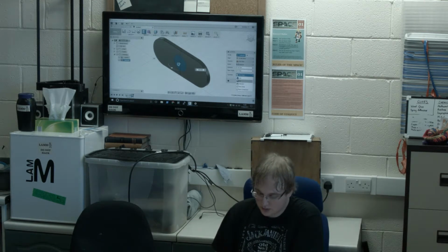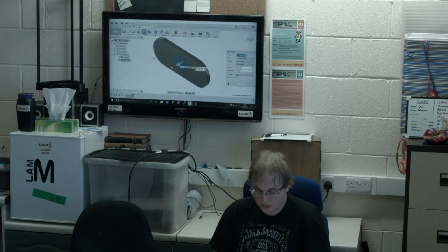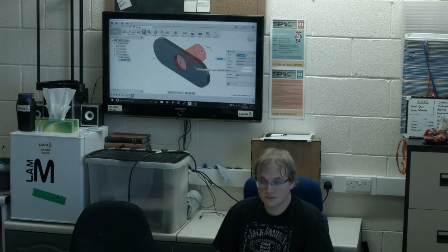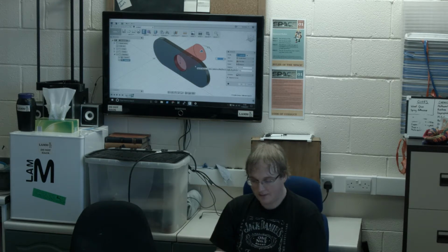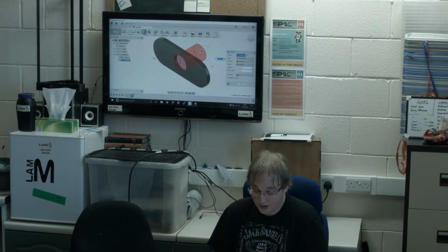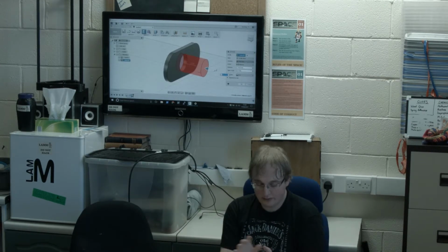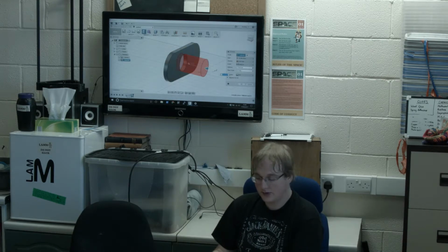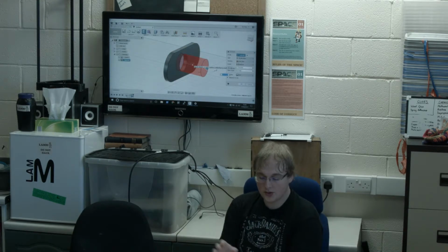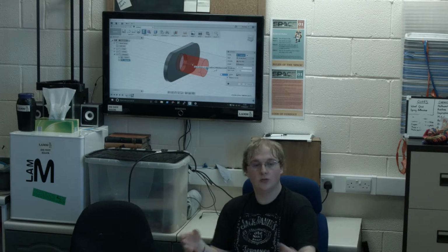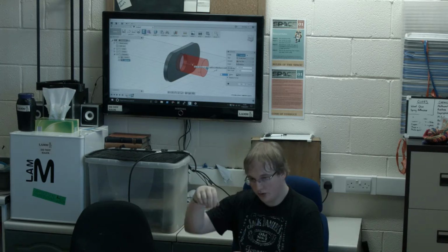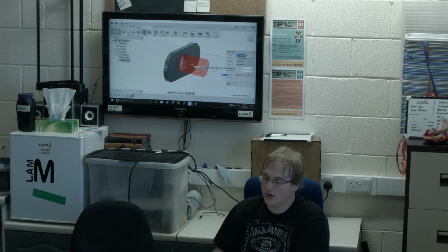For this we're going to do cut, and you can just do that. Just drag it through, done. If you want to be a little bit more stylish, the thing with this is it's now 70 millimeters. If you then change the body size to be 80, you will now have a hole that doesn't go all the way through, because it's linked to one side of it.